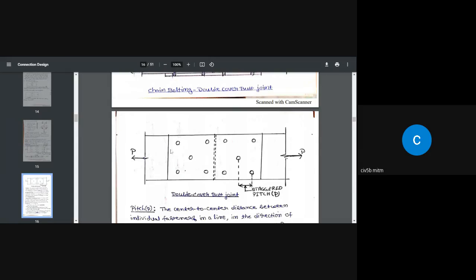Okay, this is diamond bolting, wherein we need one more bolt here to make it definitely a diamond bolting. So we can say this is staggered bolting. That is a better terminology. Staggered means there is no sequence. So we are going to put the bolts in a zigzag fashion, to increase the efficiency of the joint. You will understand what the efficiency of a joint is when we go further.